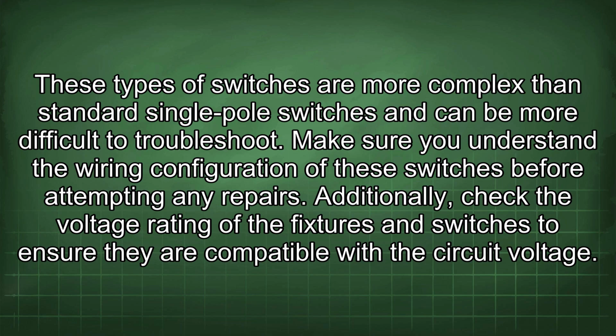These types of switches are more complex than standard single-pole switches and can be more difficult to troubleshoot. Make sure you understand the wiring configuration of these switches before attempting any repairs. Additionally, check the voltage rating of the fixtures and switches to ensure they are compatible with the circuit voltage.